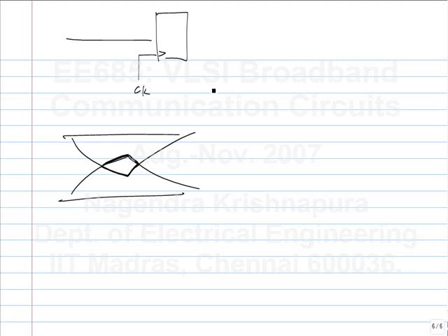Now, if you have a certain jitter in the clock, let's say you have some added noise, and you also have jitter in the clock. You would normally want to sample here, hopefully. There is some optimum place, right? So if you go too far here, both the Y opening is reduced and the probability of going off to this side is increased. So let's say you have some sampling instant, and I'll call this the sampling instant. The probability of error is the noise taking you from here to something less than 0, or the jitter taking you from this point to something beyond this or something beyond this. So it's a joint distribution between the noise and the clock jitter.